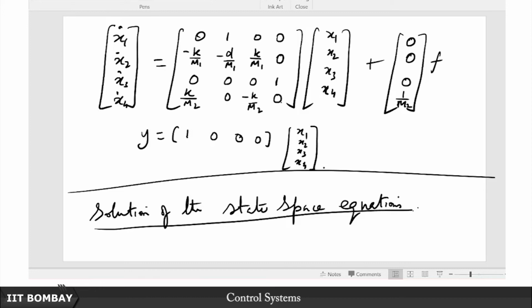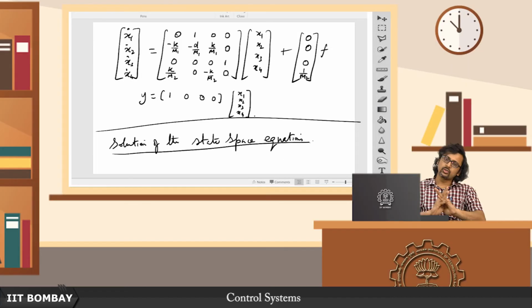But now if in trying to solve the state space equations you have to eventually resort to transfer functions, you might not feel very satisfied, because you say okay, you came up with a new method, but it seems you still have to go back to the transfer function domain. So why not let me be a little more careful in the transfer function domain itself and account for those initial conditions at the differential equation stage. Let me just take the differential equation as it is, very carefully plug in all the initial conditions and study the response.